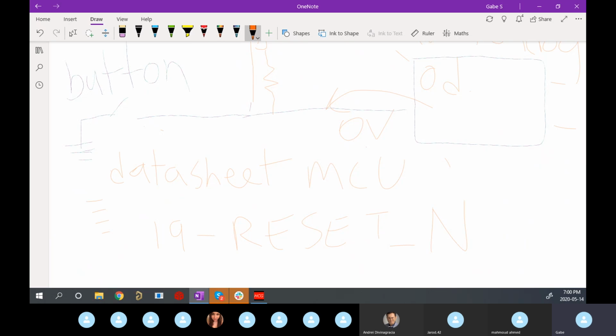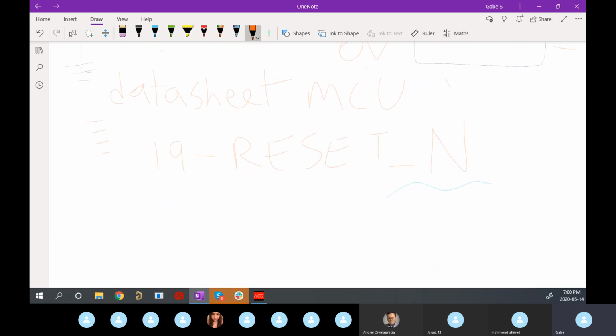This N part is what gives it away. It's almost like negated, or opposite, or not. So it's an active low signal instead of what you would normally expect. Sometimes you also see a little hash symbol instead of the N. Same thing. And then the last one is with a bar on top. These are all equivalent ways of showing that a signal is active low.